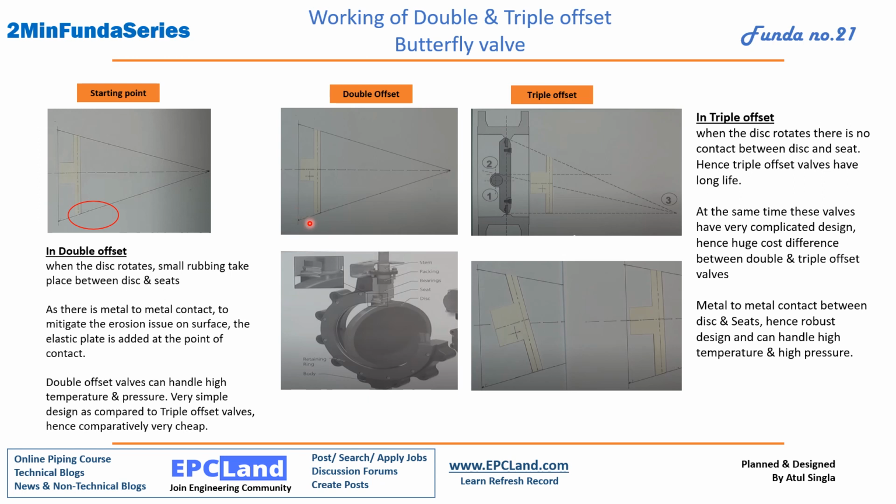Here there is small contact between disc and seat, but we are mitigating it by putting this point. So what is happening in a double offset valve? When the disc rotates, small rubbing takes place between disc and seat. As we have discussed, there is a small touch. As there is metal to metal contact, to mitigate the erosion issue on the surface, an elastic plate is added at the point of contact. So if you see, this one is added at the point of contact.